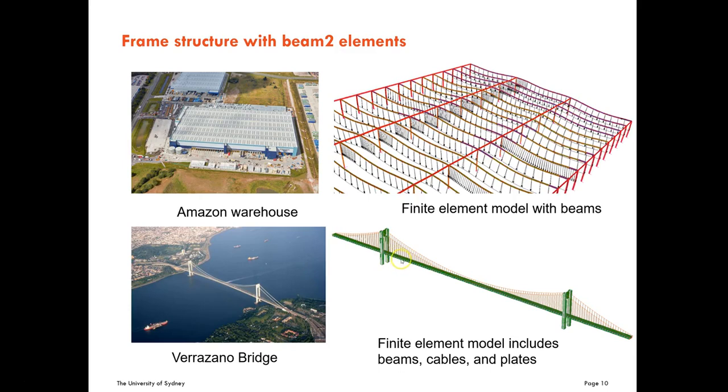The concrete and the asphalt can be modeled as plates, but you can also model them as an extra load that is applied to the frame of the deck. For the finite element analysis, we don't include the bolts and the rivets, but you have to take into account that when you drill a hole in the member, you produce stress concentrations that you have to account for.